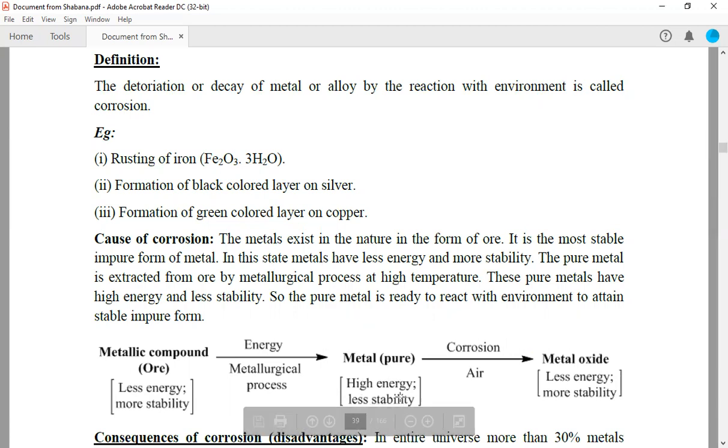As a result, when the metal is exposed to environmental conditions like dry gases, moisture, and liquids, the metal surface reacts and forms more stable compounds of the metal, which are in a thermodynamically stable state, like oxides and carbonates, more rapidly.